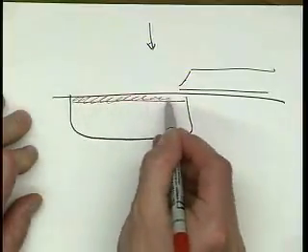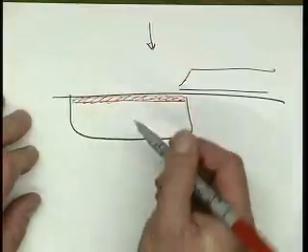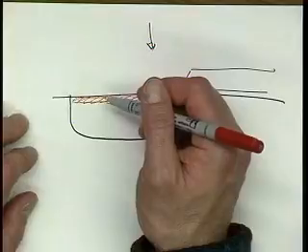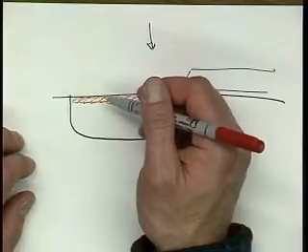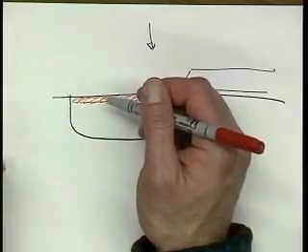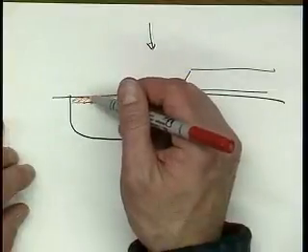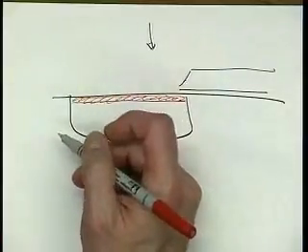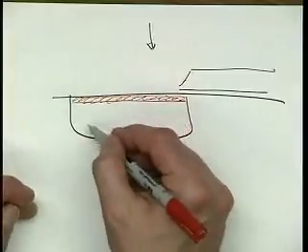So I've forgotten exactly how this is done, but a metal is put on top of the junction, usually titanium or tungsten or something like that. And then the thing's heated up, and it makes a so-called silicide. It's neither that metal, nor is it just the silicon.